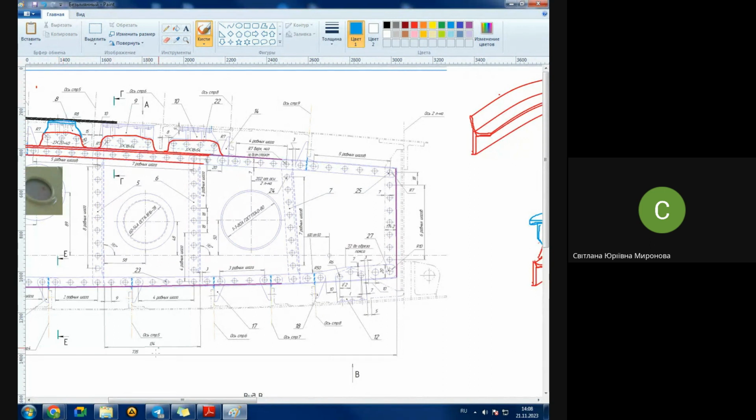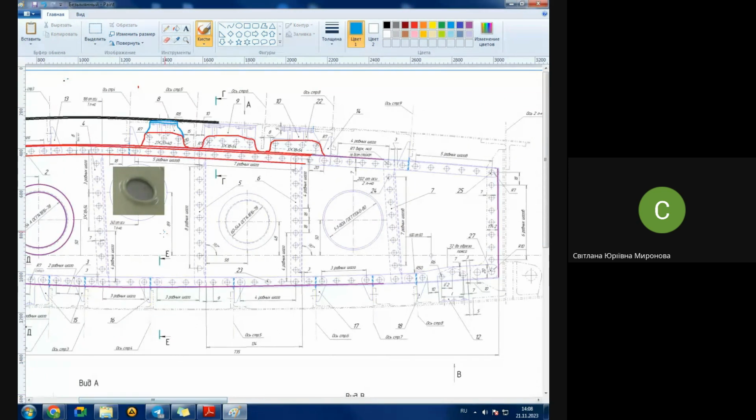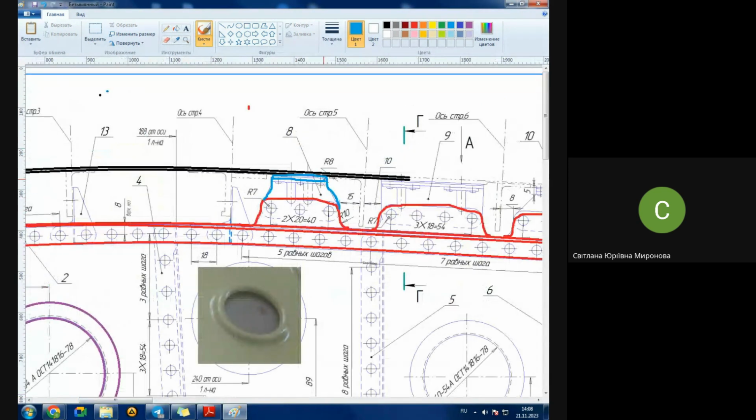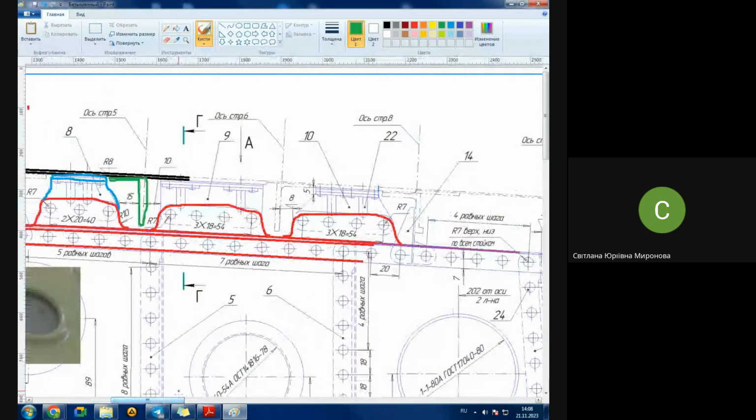On the other hand, look, anyway, the rib cap needs to have some openings, slots, to let the stringers pass, because under the skin you have stringers here. So anyway, these caps should have some openings. But to be frank, it's not a good idea to cut longitudinal elements, no, stringers are not to be cut at all. It's quite clear. They are working for bending moment together with the skin.